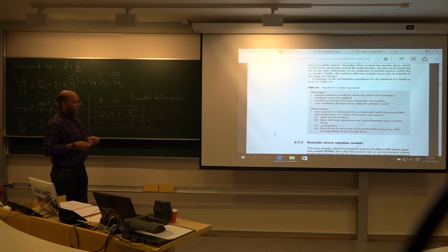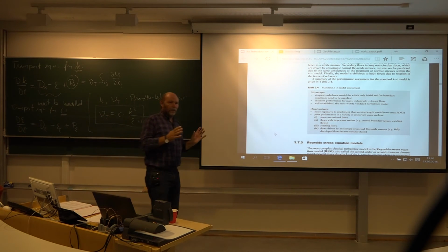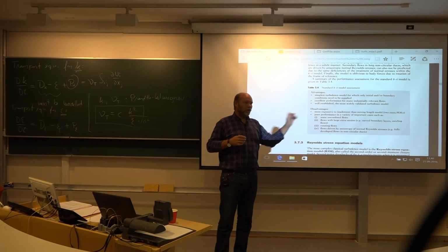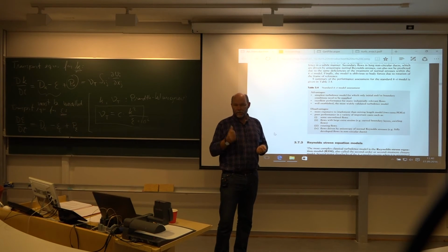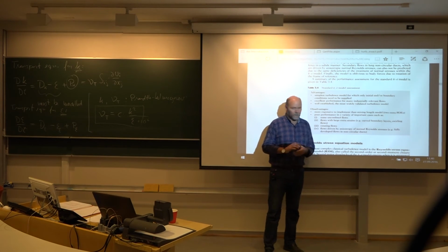Remember, for the K epsilon and K omega for that matter, they have no sense of direction. K, that's the kinetic energy, 1/2 velocity squared. And velocity squared, then the directions are lost. So it's blind for direction, meaning it's based on the assumption that the turbulence is isotropic. So if you look in this direction or in this direction, you see the same turbulence structure either way, which is in some cases a big lie. So it can't describe everything, especially when you have large elements of anisotropy.